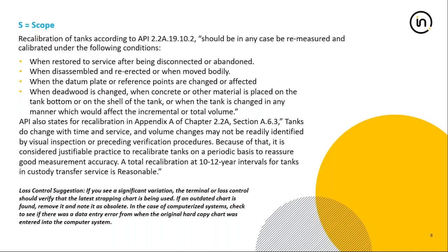Because most of the work is the same, some of our clients in the Americas have decided it's just more cost effective and more accurate and better for their loss control programs to redo the recalibrations every 5 years and skip the inspection, or just integrate that inspection into a full recalibration of the tank. And I think that's a very, very good practice to have.